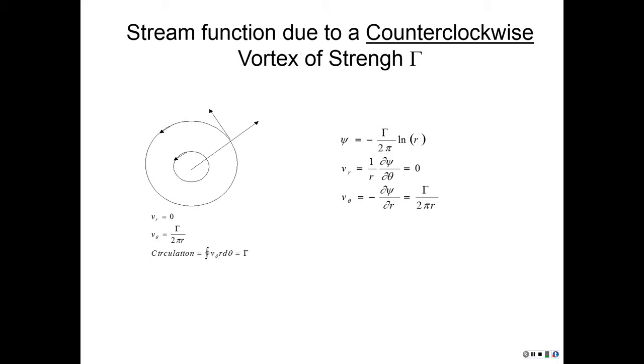Now we have all these vortices on the surface, so we need to come up with a suitable strength or a stream function. So let's say you have a counter-spinning vortex of strength gamma. It produces a velocity pattern that looks circular like this. The vortex is at the center, spinning counterclockwise, producing a circulation like this.